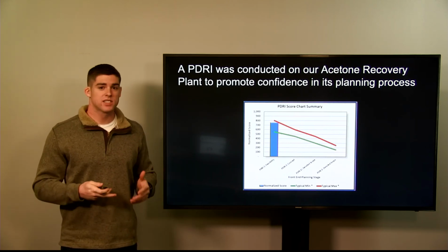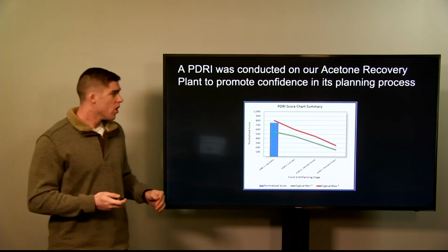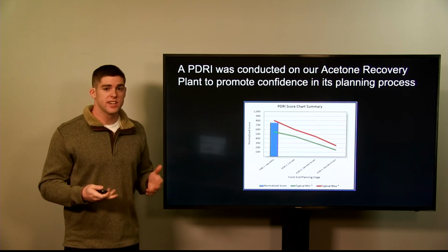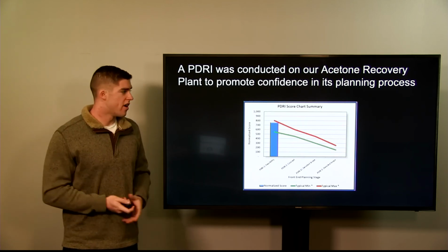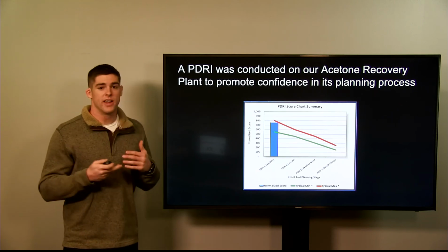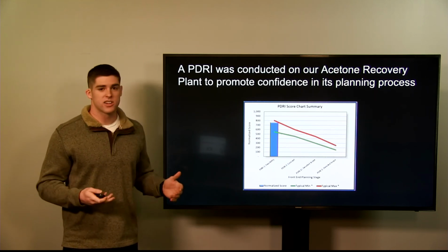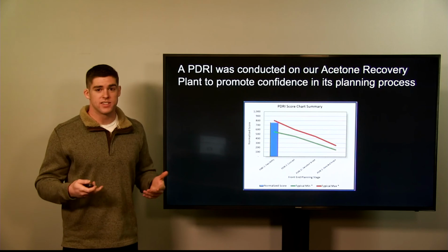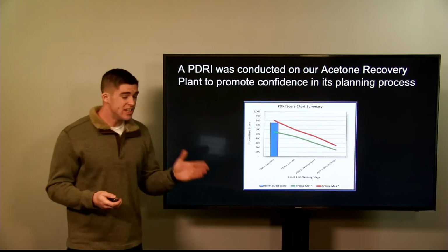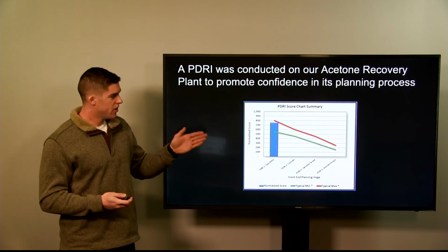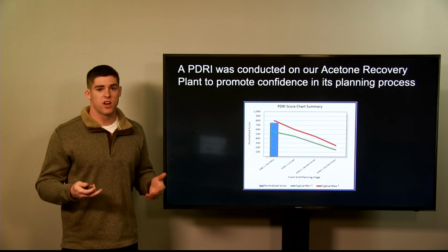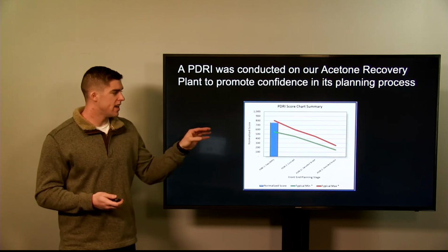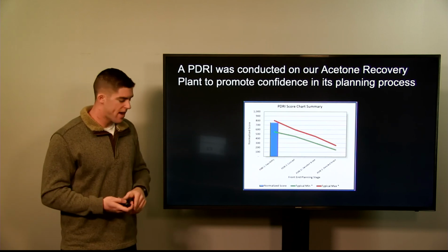Lastly, since this is a capital estimate project that we are doing here, we wanted to do a PDRI, which is a project definition rating index, on our project in order to assure confidence for our investors. That way they know going into this that they can have trust that we've gone through all factors within the front end planning process in order to build confidence in their investment. So through each gate, we'd go through and do a PDRI, and you can see that after gate 3, after we'd focused on all of our mass balances and finalized our actual design, we had a PDRI rating that was in the typical limits between the min and max there.